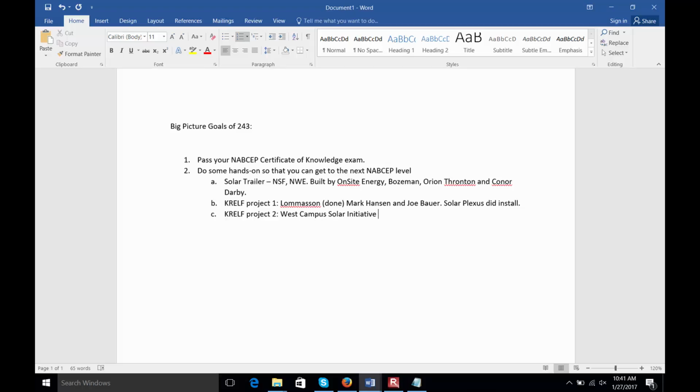Remember the TV show? What did CSI stand for? Crime Scene Investigator. Okay, so WCSI. And his goal there was to hit the legal limit on installations, which currently in Montana is 50 kW. You could put a larger array in, but then you actually become a primary source for the grid. You now have to have a PPA in place. 50 kW is the maximum if you want to be what's called net metered.